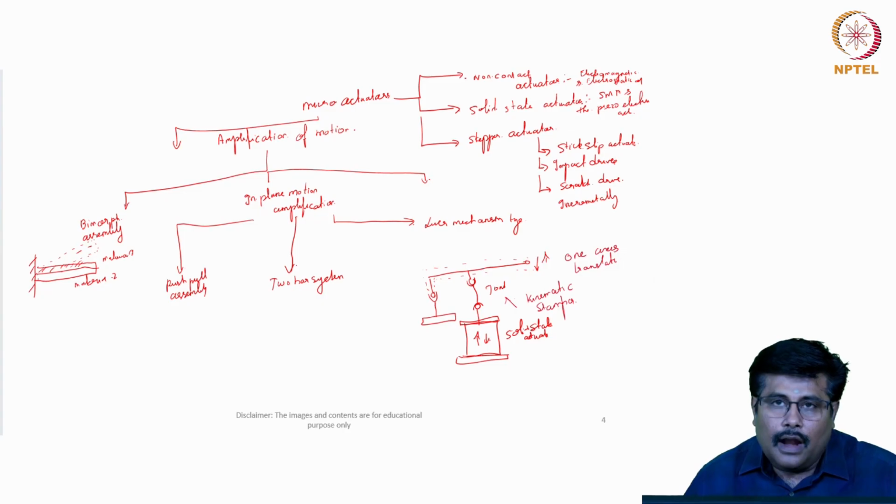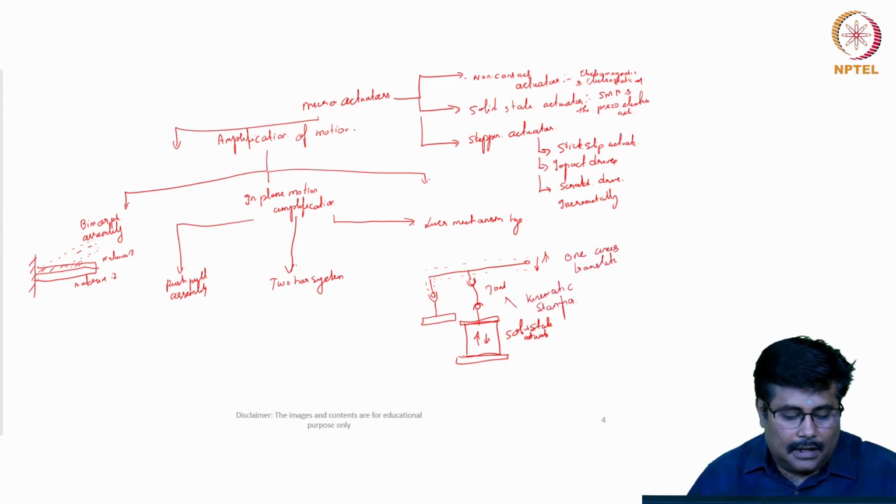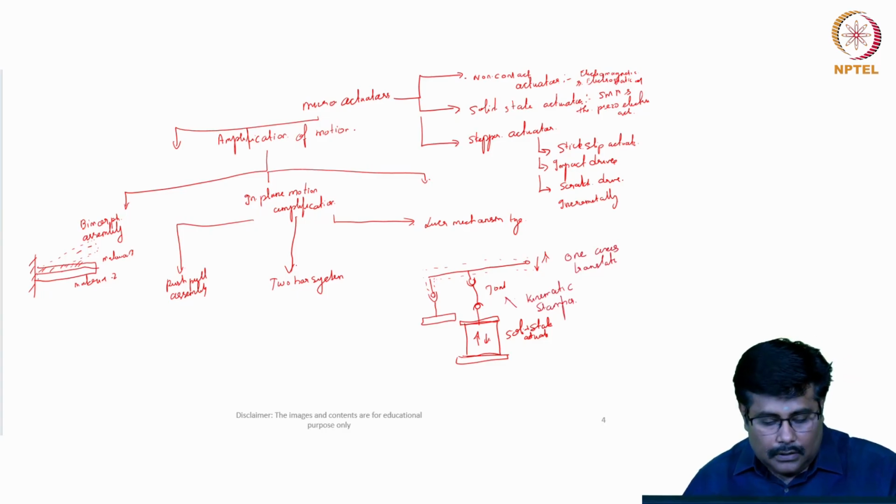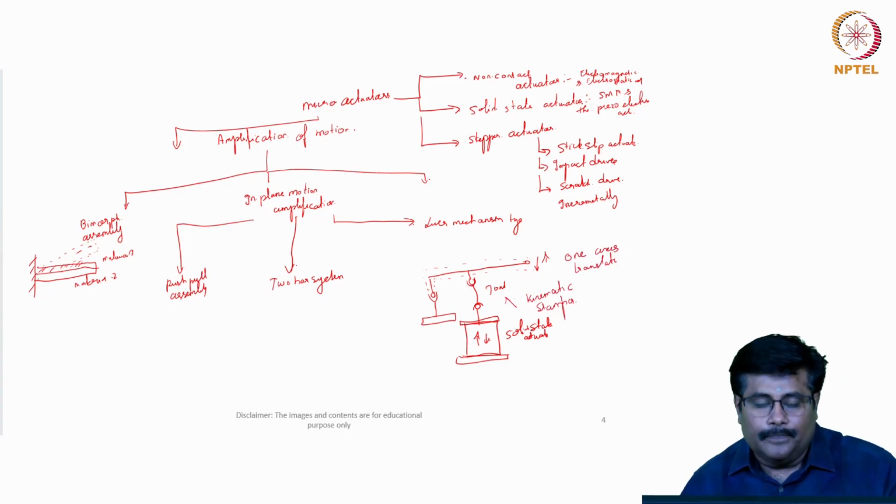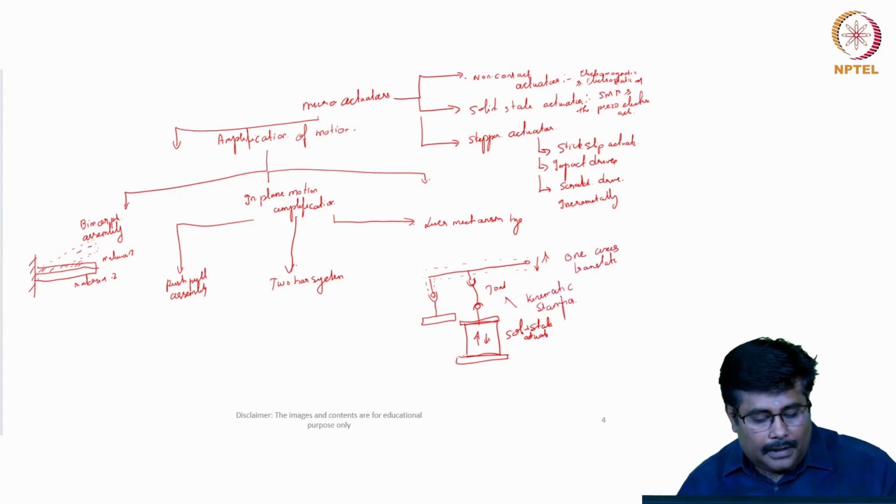The lever amplification is realized by using a pivot joint. A lever pivots around a point anchored to a fixed body. Two pivots are used to interface the linear motion of the actuator with the angular motion of the pivot. The actuators forming the input of the mechanism are attached at one end, while the output of the mechanism can be any point on the lever.